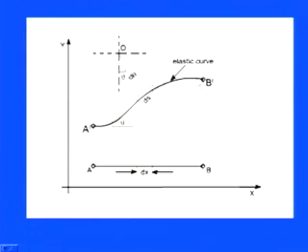In that curvature shape, the assumption was that whatever curve is coming, either the deflection curve or the elastic curve, has to follow elastic deformation or elastic deflection terms. That's why the deflection curve is also known as the elastic curve, as it is written here. So A dash and B dash is the deflected curve. In that, the deflection depends on d theta. Here the d theta is there, and if you take any origin as a reference point on this curvature, then we can see how much change there is between the straight portion and the deflected portion.